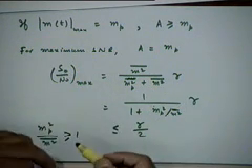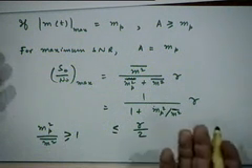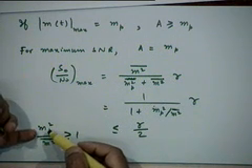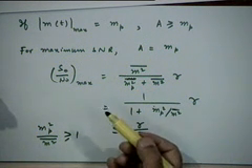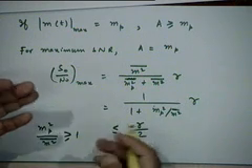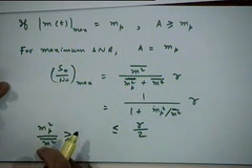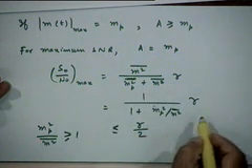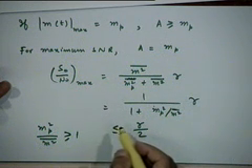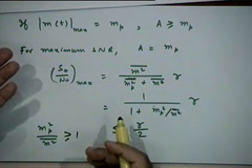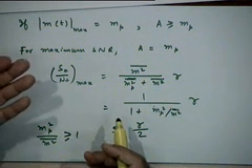Typical situations will actually be more than 3 dB, because very rarely will you have mp square by m square bar equal to 1. It will typically be much greater than 1, at least somewhat greater than 1. So, depending on the actual value of this ratio, the SNR reduction or the power cost associated with use of AM with carrier is more than 3 dB.